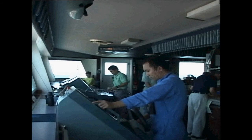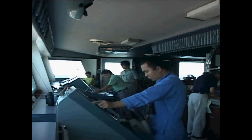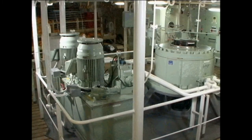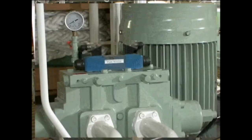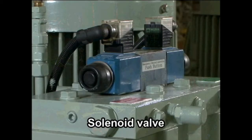Even when the steering stand cannot be used on the bridge, it's possible to steer the rudder by communicating between the bridge and the steering engine room. In this case, solenoid valves of the hydraulic apparatus in the steering engine room are controlled directly. It's important that emergency steering practice drills are carried out regularly.